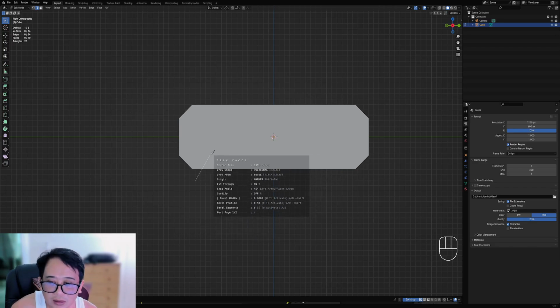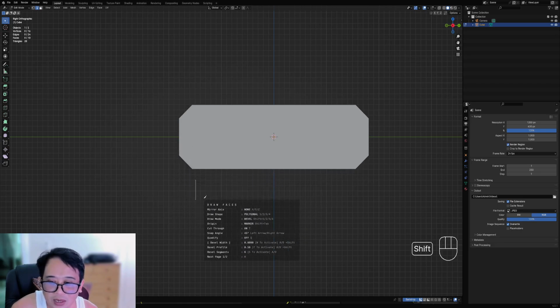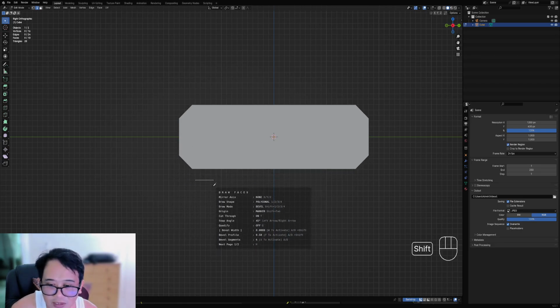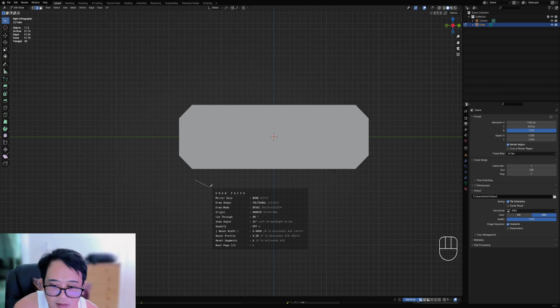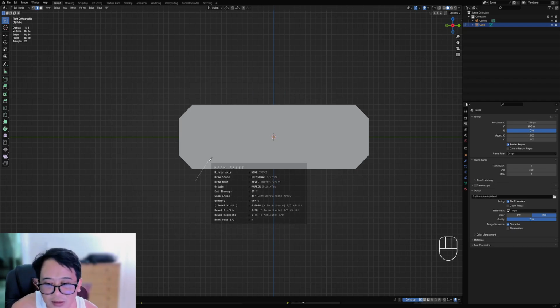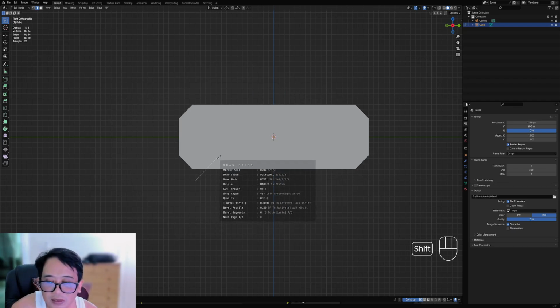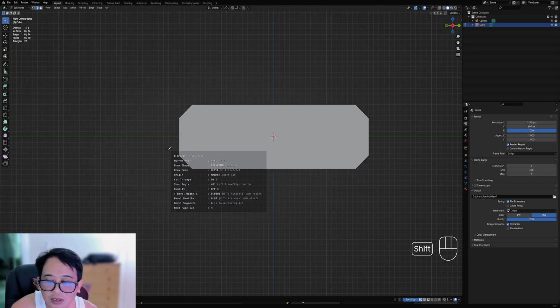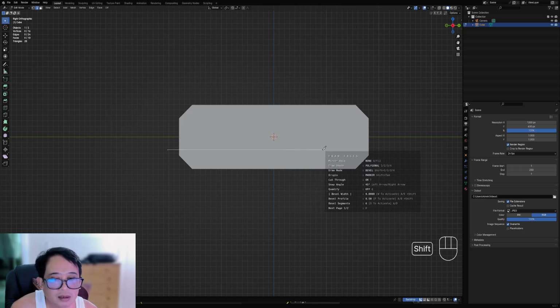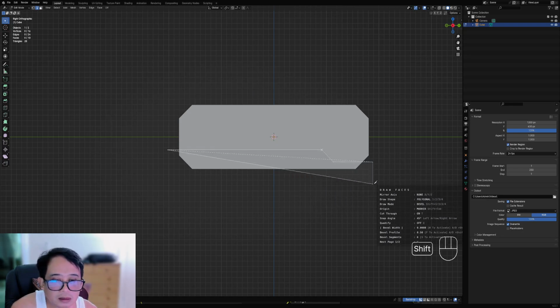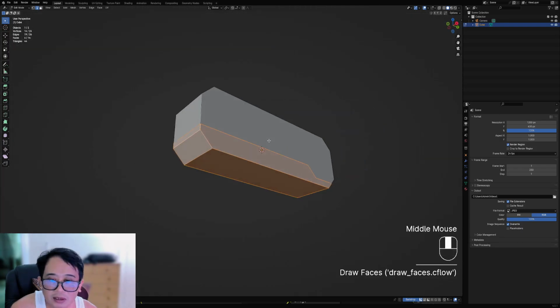and shift to activate snapping in 45 degrees. You can change the snap angle using the arrow keys, and it will go up and down in increments of 5 degrees. So mostly I just use 45 degrees. So pressing shift will allow you to use the snapping.